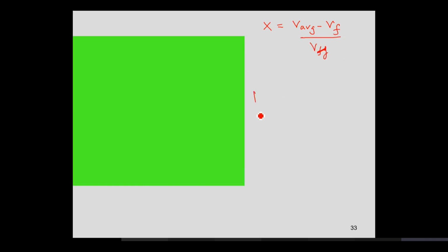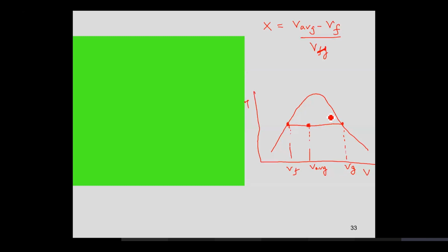Now, if I have the temperature specific volume plot over here, and this is the isothermal line, the phase transformation line, here I have, let's say, Vf, this is Vg, and I have my mixture somewhere over here. Let's say I'm assuming it. So this mixture would have the value of V average. I represent the saturated liquid as A, the V average value as B, and the Vg value as C.